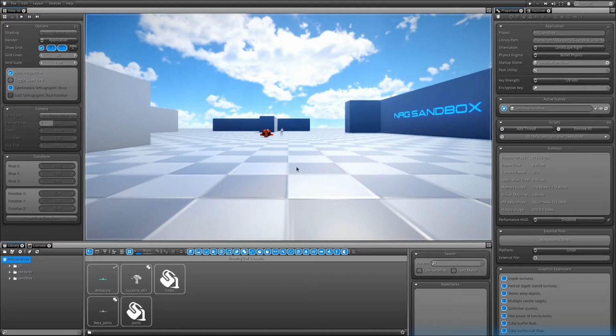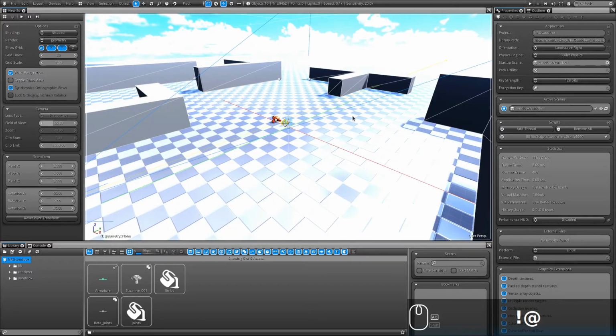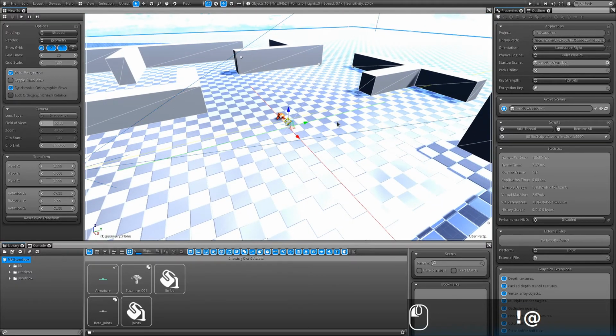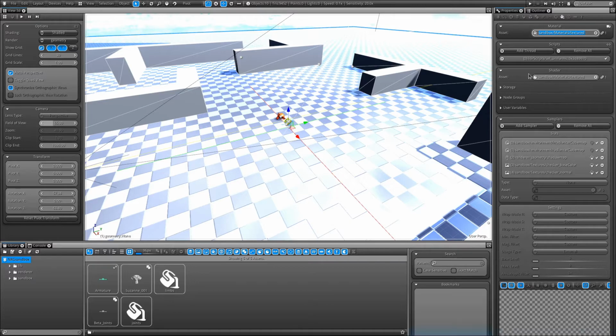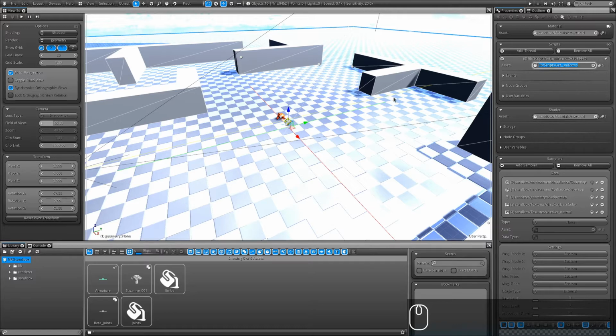So to get us started, we are going to go in edit mode on second render layer, and we're going to inspect our floor material here, since it's the closest one that we have by default in our scene that contains a base color texture and a normal map. I am going to go under properties and material and inspect that textured material. And I can see that this material is also connected to the set uniform script, just like any other object here. So I'm going to need to have that connected while importing my asset.